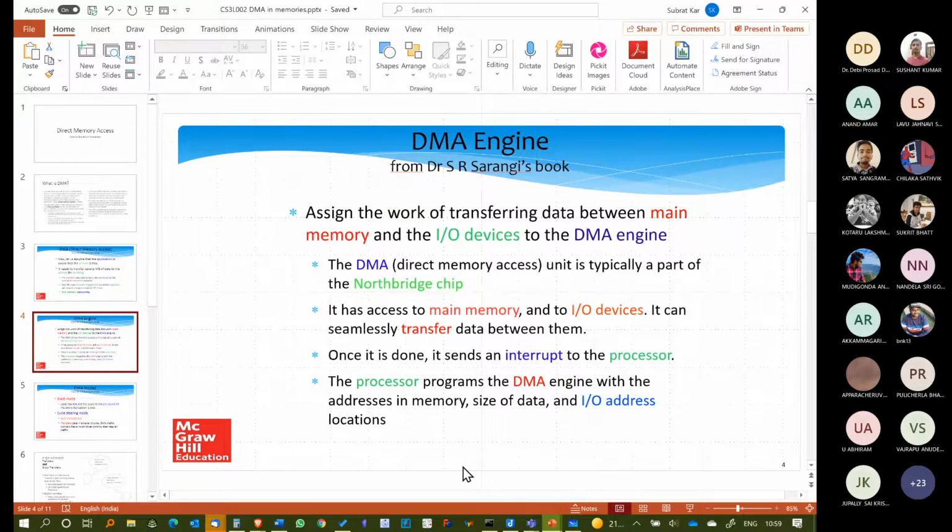Right? What is the word engine? Well, engine is a term which we use for something which drives something. A car engine drives the car. So a DMA engine drives the DMA. So I can say a memory controller engine, a data sorting engine, a Fibonacci sequence generator engine. Right? It doesn't mean engine in that sense. It means it's a thing which turns out things. It's a finite state machine which turns out things. So we will often find this word, network engine. Right? Engine means something which handles DMA.